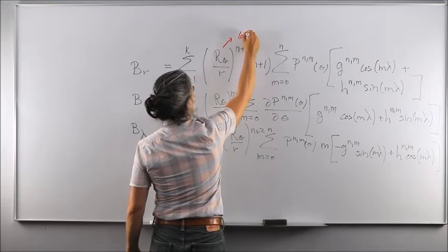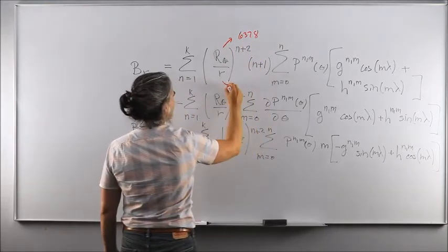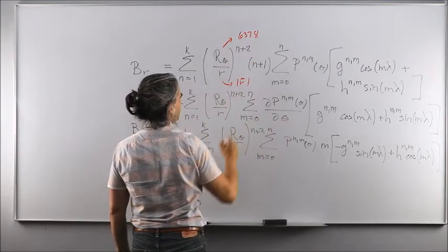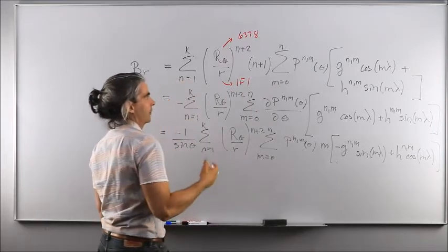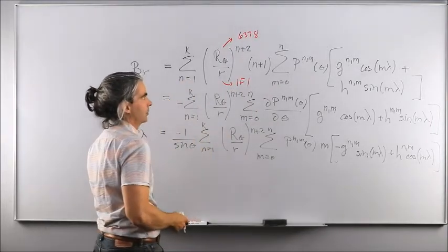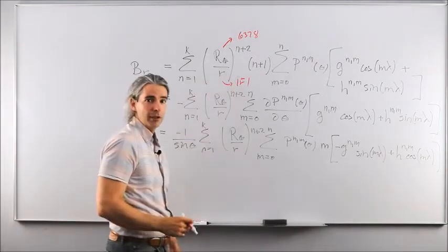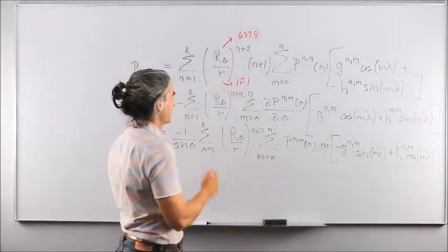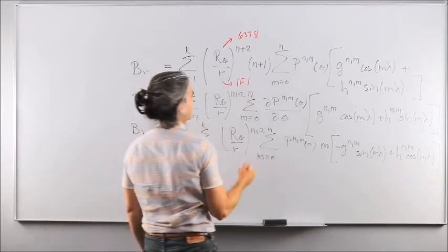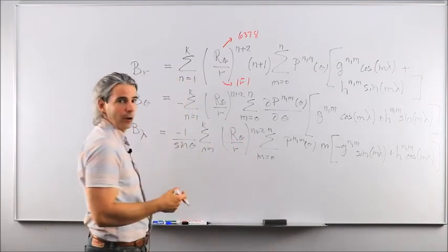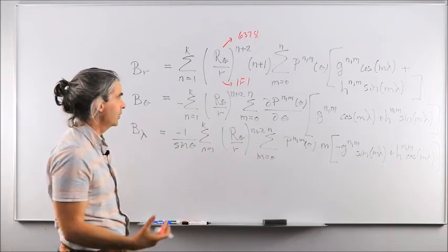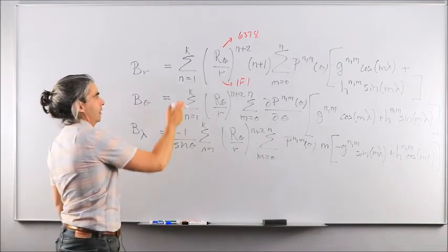This is your 6,378 kilometers. This is the norm of the position vector at the current time for the spacecraft with respect to the primary attracting body M1, obtained by solving the two-body equation from orbital mechanics. It's up to us to decide how accurately we want to model the magnetic field of the Earth by selecting a degree and order.